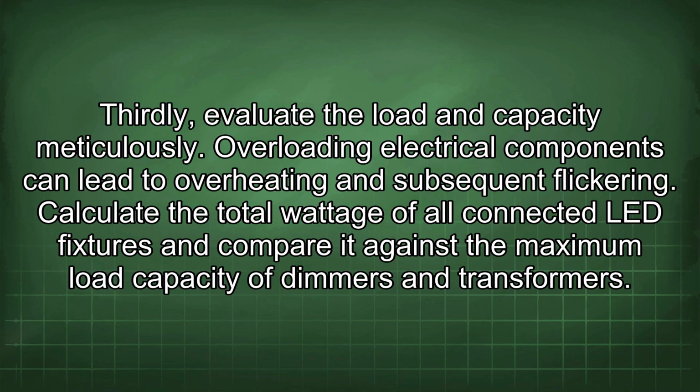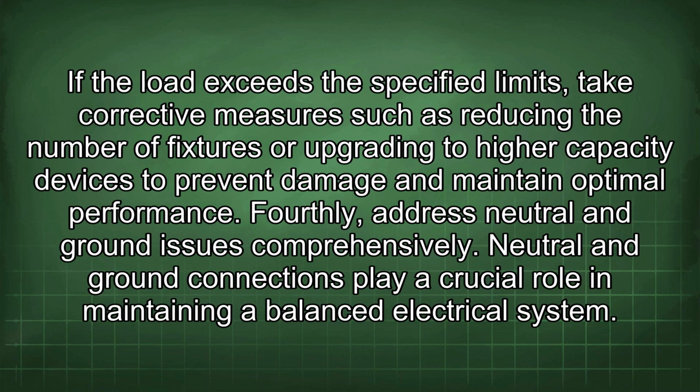Thirdly, evaluate the load and capacity meticulously. Overloading electrical components can lead to overheating and subsequent flickering. Calculate the total wattage of all connected LED fixtures and compare it against the maximum load capacity of dimmers and transformers. If the load exceeds the specified limits, take corrective measures such as reducing the number of fixtures or upgrading to higher capacity devices to prevent damage and maintain optimal performance.